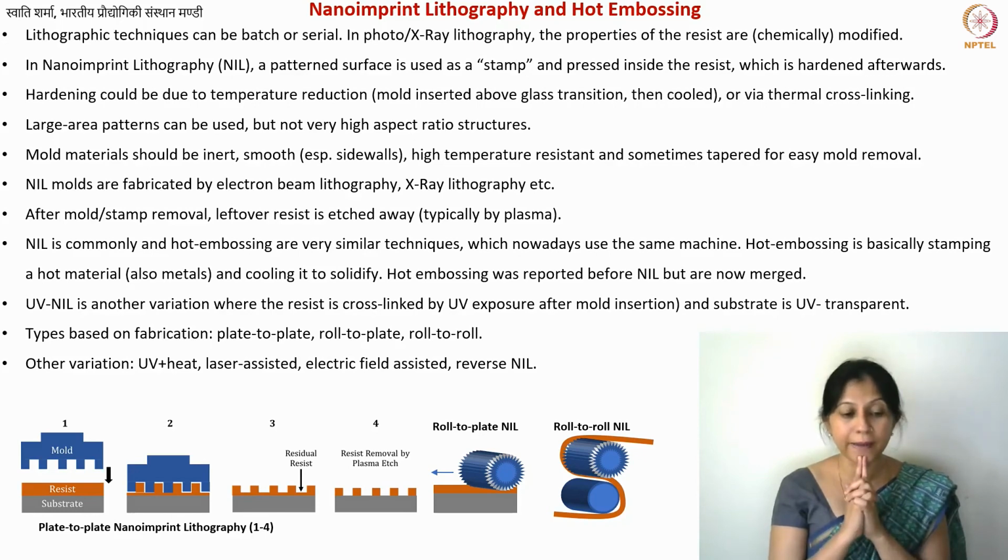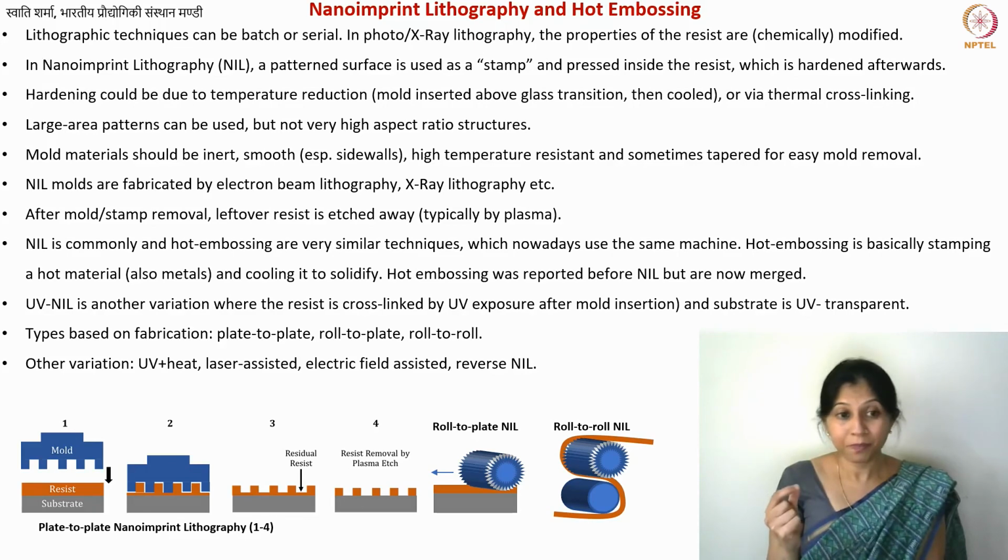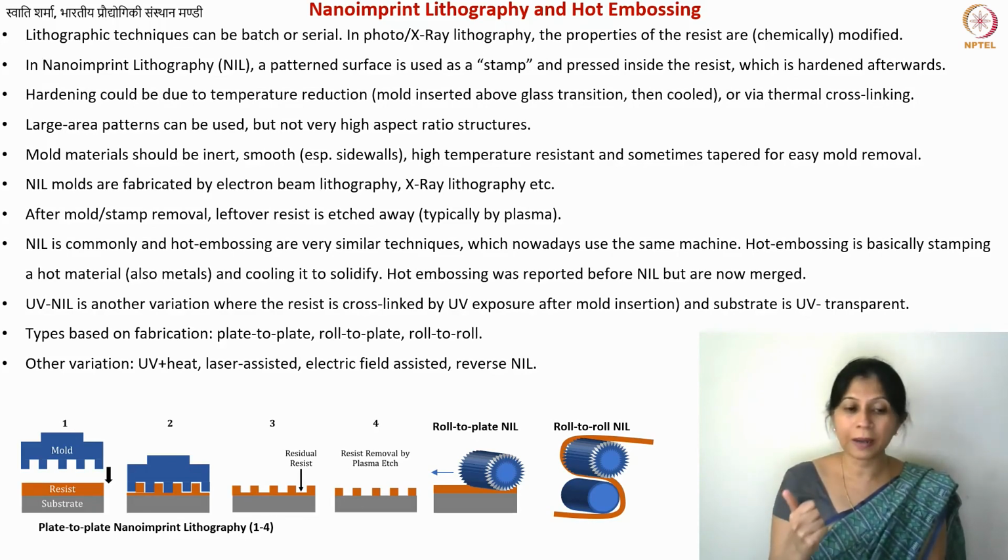The point is that nano imprint lithography patterned structures have been converted into glass-like carbon, again using the same technique that we use for photolithography. We just need to do the carbonization, put it in the furnace, 900 degrees, inert atmosphere. When these structures are converted into carbon, they become very useful, because, number one, polymer structures were insulating in most cases, but our carbon structures are conductive. So already we can have so many other applications.